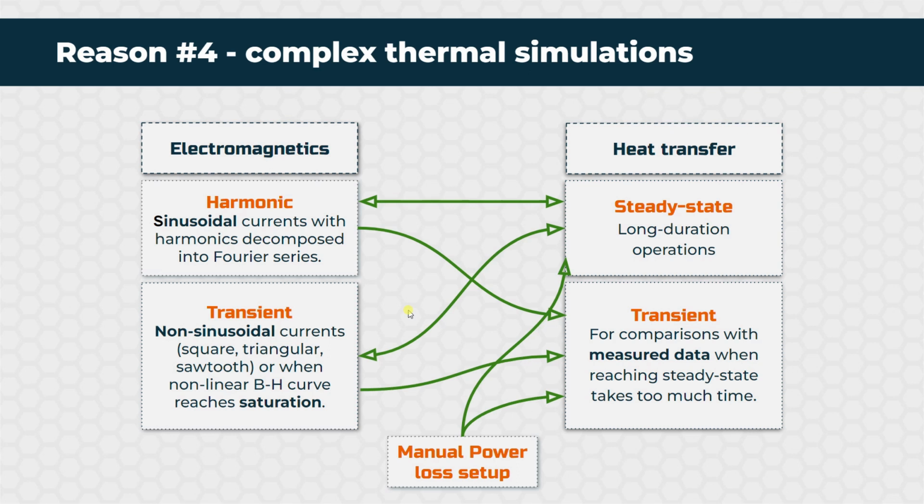And finally, the fourth reason why you would consider 3D FEM software is coupling with thermal simulations. Let's say there are not so many options for how you can accurately calculate heat transfer. The most accurate could be solving the so-called conjugate heat transfer problem, when you have heat conduction in solids and fluids. Fluids, like air, take some heat out of your component. Those simulations are very complex and very complex to set up.